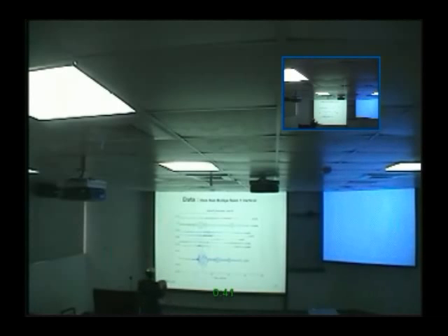This is the vertical at span number 1. This is the vertical at span number 2. Look at this one, it is more than 0.04. This is a very heavy truck passing by. And this is a small truck and these little cars passing by. This is span number 2, span number 3, and span number 4. They are all different.